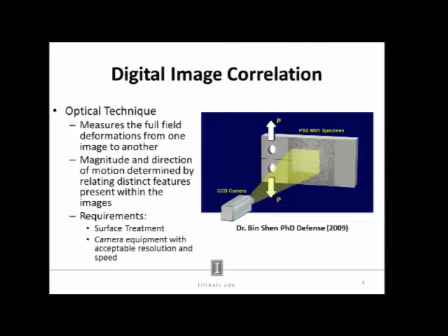But if you're dealing with, say, a limestone aggregate in an asphalt mixture, you see a lot of pixel values that are close to 255. Specifically, if you're using a 12.5 to 19 millimeter nominal max aggregate size mixture, you could be dealing with aggregate that takes up quite a bit of your image, which affects your ability to correlate well, such that the cross-correlation coefficients that we use in digital image correlation are kind of lost.